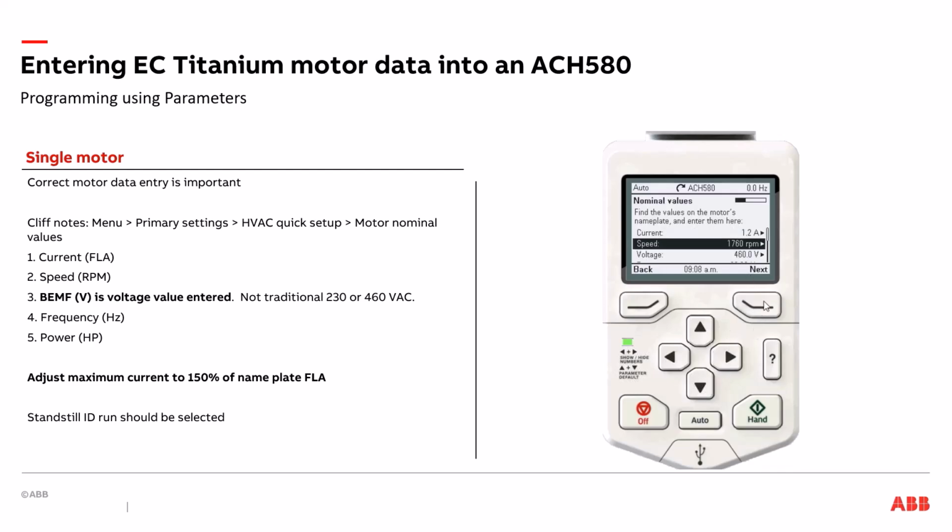The RPM is 1800 RPM even. The voltage. This is my back EMF voltage. On my motor nameplate, it was 248. The frequency is 60 hertz.